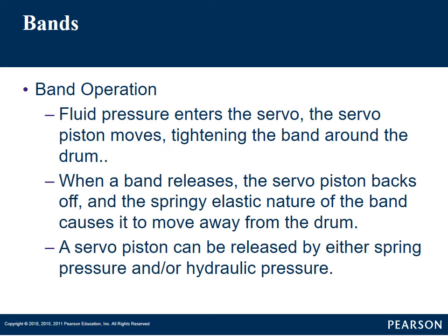So it would drag on the drum, or the servo rod that applies it could come out of place and then fall out or something silly like that. But there's a reason those bands have some sort of spring nature to them, so they can release and move away from the drum.